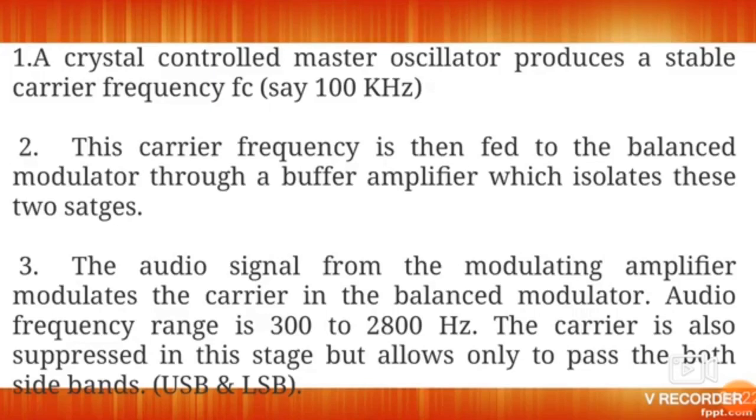The bandwidth of the transmitter and the channel is only FM in case of single sideband, whereas double sideband with carrier requires 2 FM. So the bandwidth requirement is half that of the previous two categories. The power of the suppressed carrier and sideband is saved, hence the transmitter power requirement in SSB is saved.